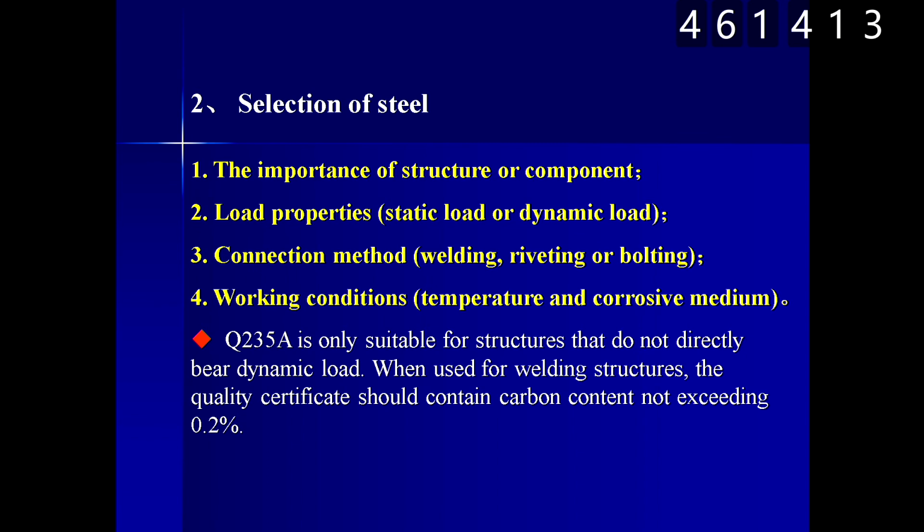The most widely used in China, for almost 20 years, we normally use the Q235A steel, because it is suitable for most steel structures and can bear cyclic loadings, and it's also very easy for welding structures. The quality certificate should state the carbon content standard, 0.2%.